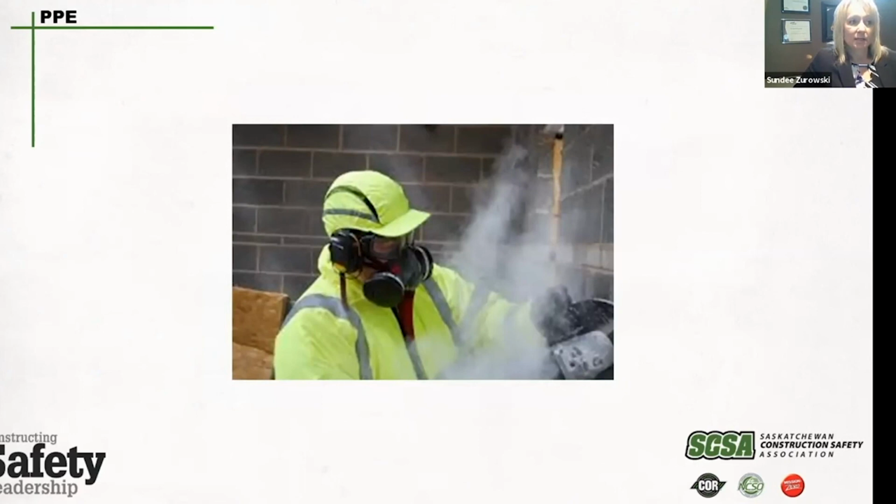If it is not practicable or feasible to substitute, use engineering controls or change your work practices to control the exposure. Personal protective equipment may be needed and is always your last line of defense. Many types of respirators are available, and it is important to select the correct ones for the work being done.